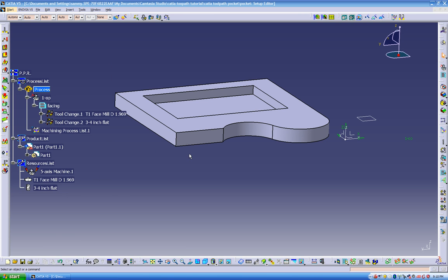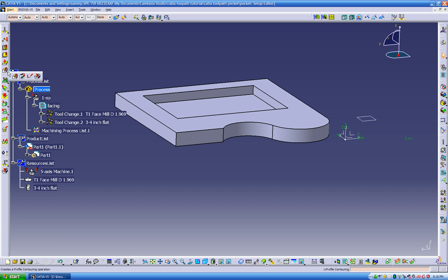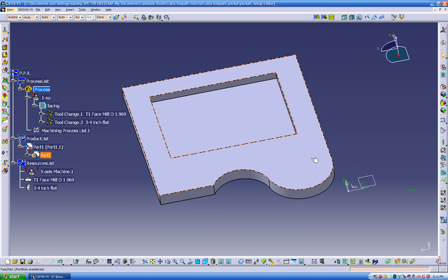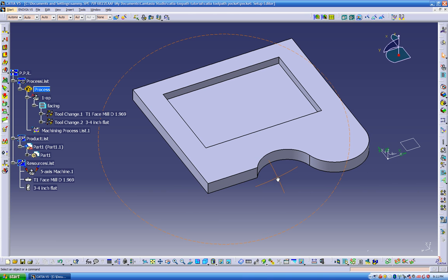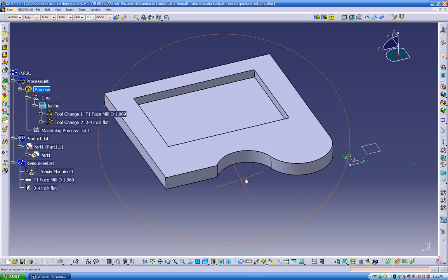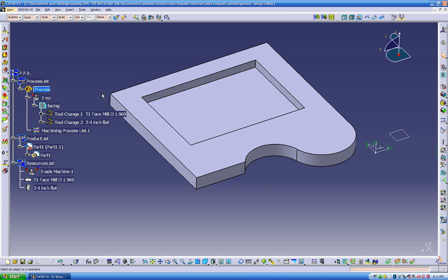Our next option is gonna be the profile contouring. We got a couple more options in here, but not for now. So we're gonna give it a try to walk around this part and remove the excess material. What I'm gonna do first, I'm gonna machine this edge, and then I'm gonna machine this edge in here. And assuming they're gonna have two clamps to hold the part over here, then we're gonna stop the program and then swap the clamps and machine the leftovers.